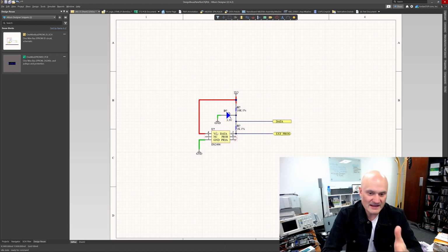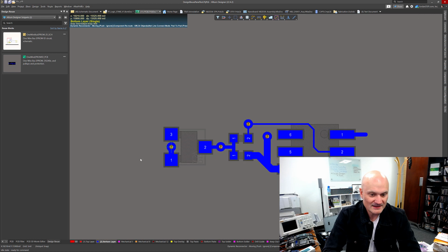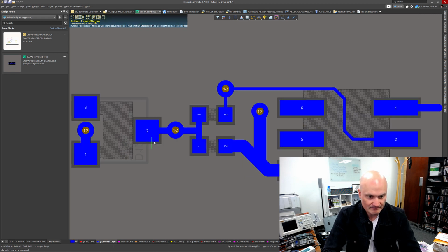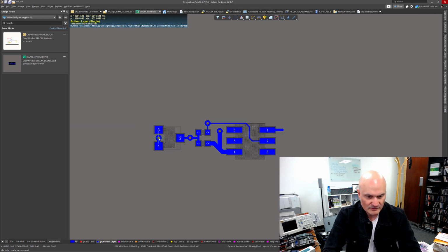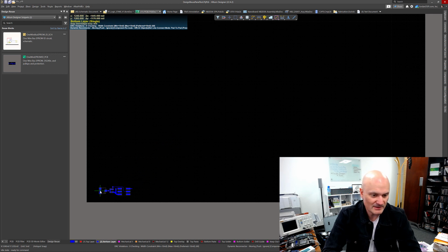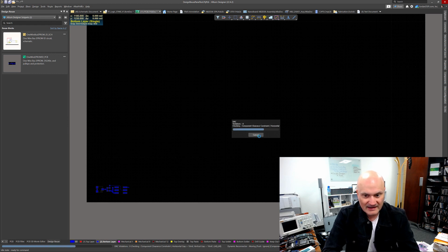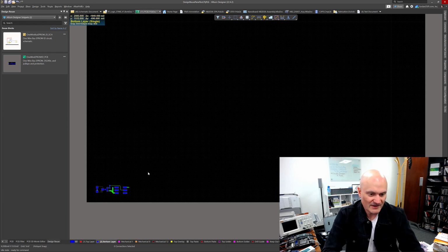And that's the schematic part. Then on the board side, I've got the place menu for the PCB part. Let's go zoom board, ZB. I don't know why it thrust me into deep space there, but anyway, let's just say I was placing that here. And I'm going to have some DRC violations because I don't have nets or anything in this brand new board. So just ignore that for now.